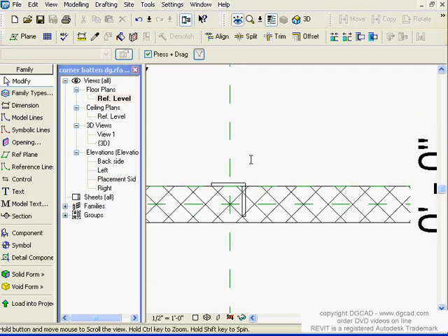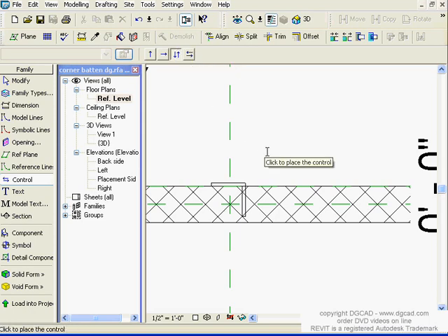One more thing, let's add our flip controls in here. So over here we simply have our control buttons. This is like what you would use on a stairway. It's a directional flip, whereas this is more like this will flip direction. This just flips about the object. So I'm going to take one of these and say, okay, I need to have one of those, and I'm going to place it there and click on here. And it really doesn't give you any sort of snaps or anything. I'm just going to click that, put it there, and I'm going to save it.